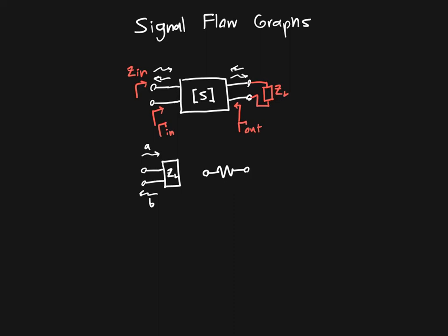So you've got this node A, and then you travel along this branch, and it's similar nomenclature to circuit analysis, to this other node B. So A and B are your two signals that you're interested in. And then along this branch, you've got a multiplication factor, gamma. So B is nothing but gamma times A.